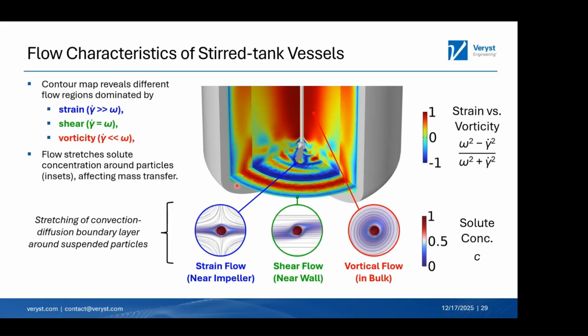This can get exaggerated. So in the most general sense, for shear flow example, you can get interesting closed orbit phenomena where concentration boundary layers don't stretch. And so you have a much reduced extent of mass transfer when strain and vorticity are in balance. But in the case where you have rate of strain and vorticity along that strain field, you'll get stretched boundary layers, thinner boundary layers, and enhanced mass transfer.